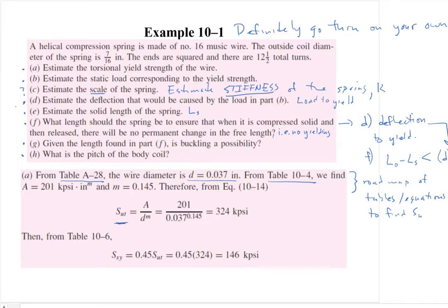to find SUT. And in almost every spring application that you would be doing for this chapter, finding the ultimate tensile strength would be one of the first things. And then here they're using S sub SY is 0.45 SUT. As I mentioned before, that's in this slide here.